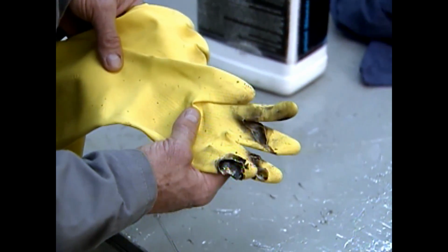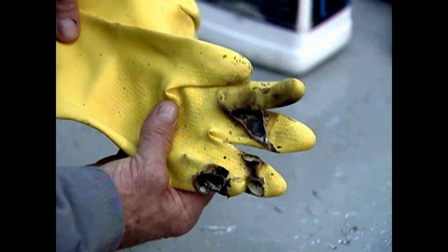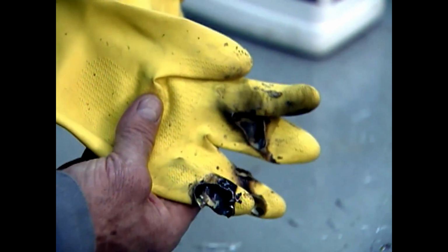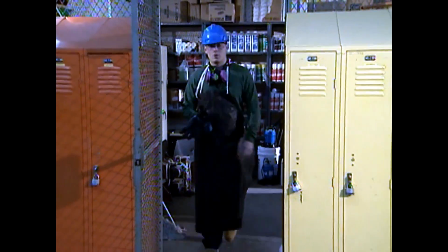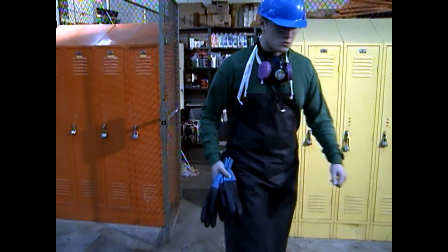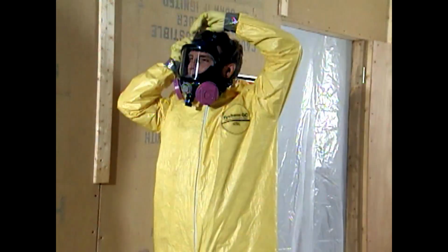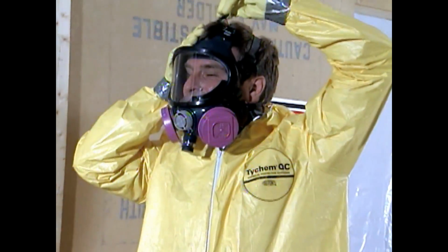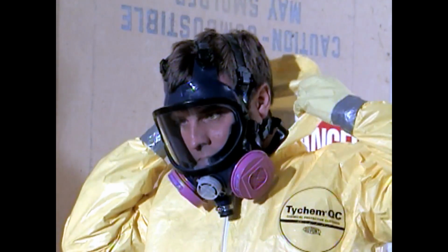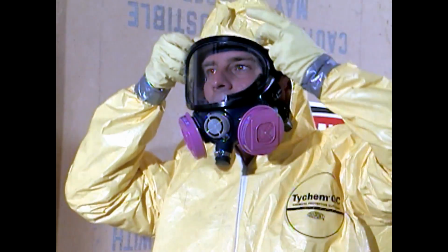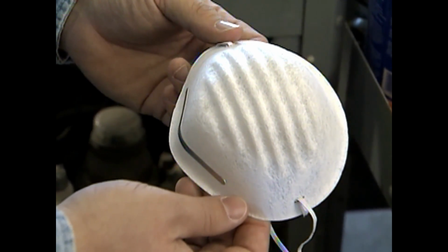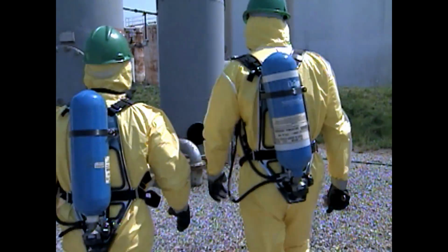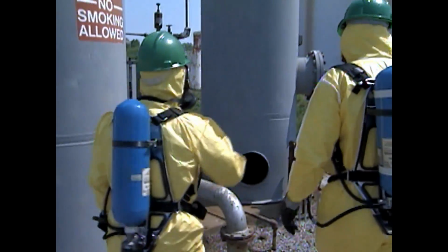Some rubber gloves, for example, can fall apart when exposed to certain corrosives. Some chemicals require aprons or full-body coverings to protect you from splashes or contamination. You may need an air purification device in areas where normal ventilation will not protect you from harmful vapors. These devices can range from simple air filters to respirators, or even a self-contained breathing apparatus.